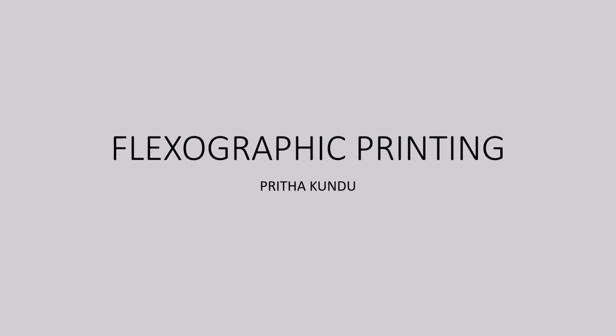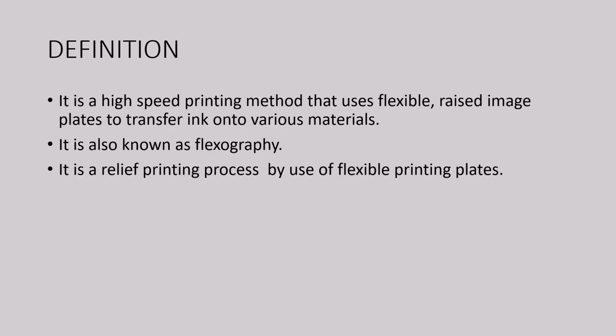Today we are going to discuss the flexographic printing process. What is the definition of flexographic printing? It is also known as flexography. It is a high-speed printing method that uses flexible image plates to transfer ink onto various materials, and the materials on which the ink is transferred may be paper, film, or foil. It is a relief printing process using flexible plates.